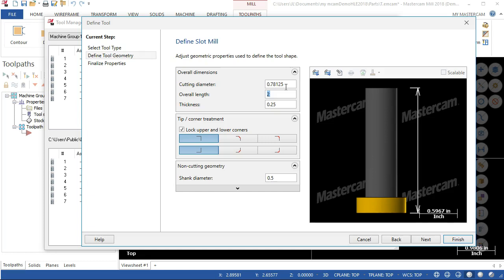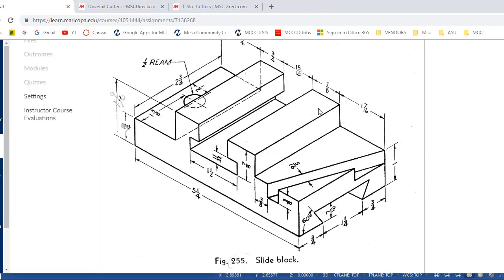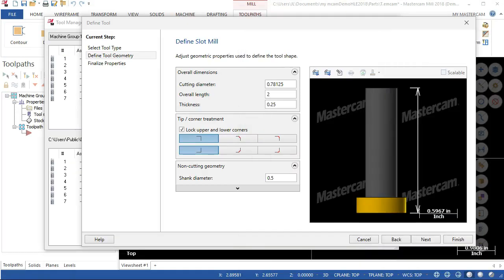That seems like it's going to be pretty close. We also have to consider the undercut on these. We're 1.5, and then the 15/16, so that would be a 1/4 inch engagement, plus another would be about 281 on the depth of the slot.